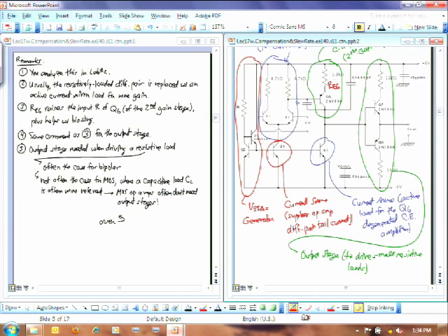You want it to drive small loads. In other words, you're going to have a next stage coming after this that's probably going to have some transistor input there. Or not, right? But it's going to present some kind of input resistance to this whole circuit. And so what do you know about voltage amplifiers, which is sort of what an op-amp is? It's a voltage amplifier. What's the ideal output resistance for a voltage amplifier? Should be 0, very small.